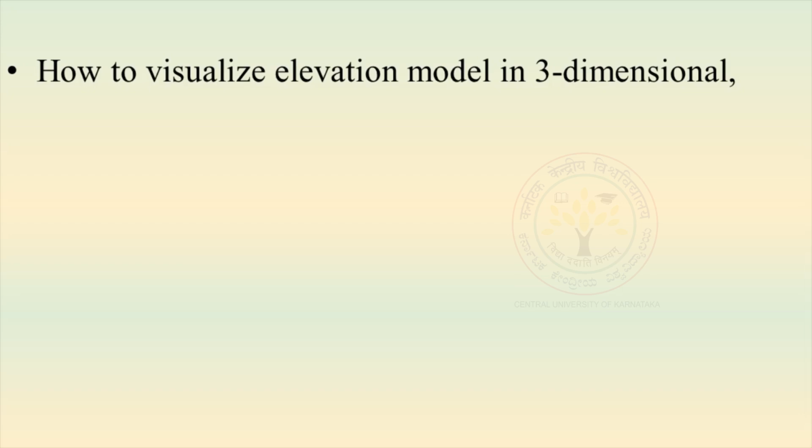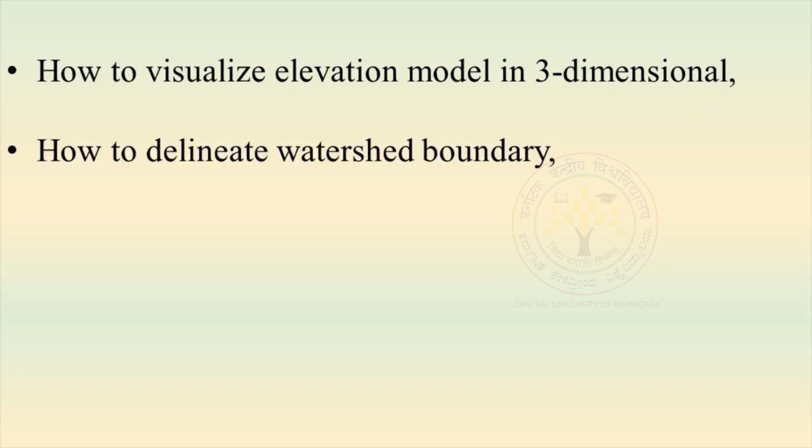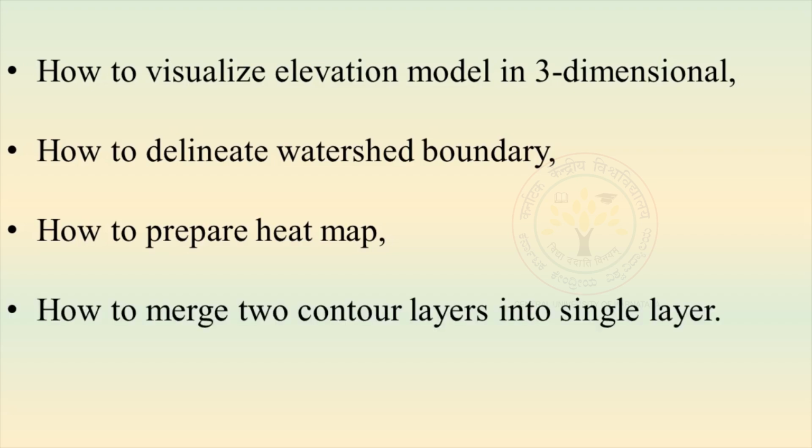In today's class, we have discussed how to visualize an elevation model in 3 dimensions, how to delineate a watershed boundary, how to prepare a heat map, and how to merge two contour layers into a single layer. To know more about the techniques used in the class and related information, visit www.qgis.org.